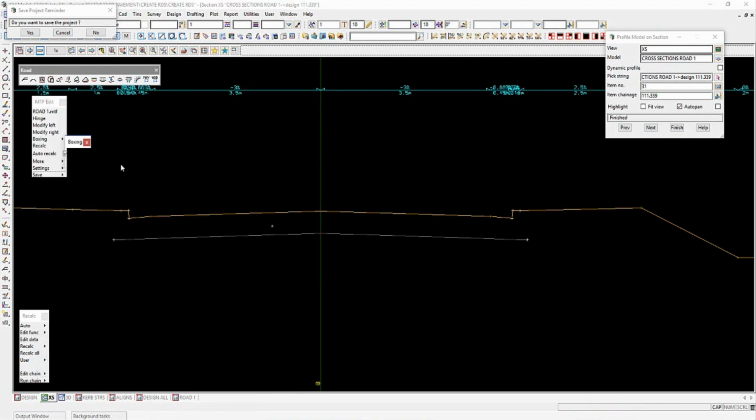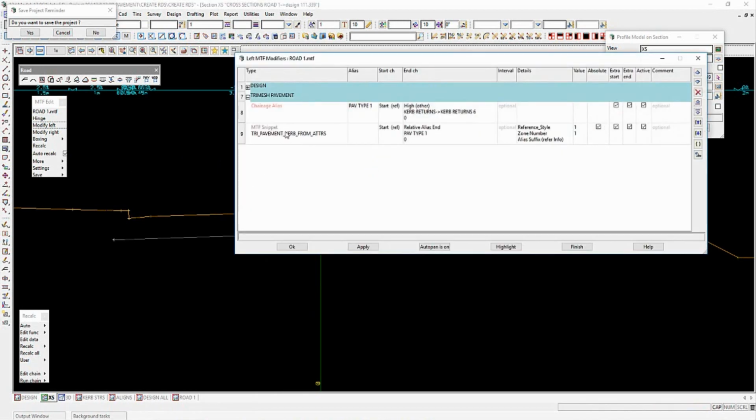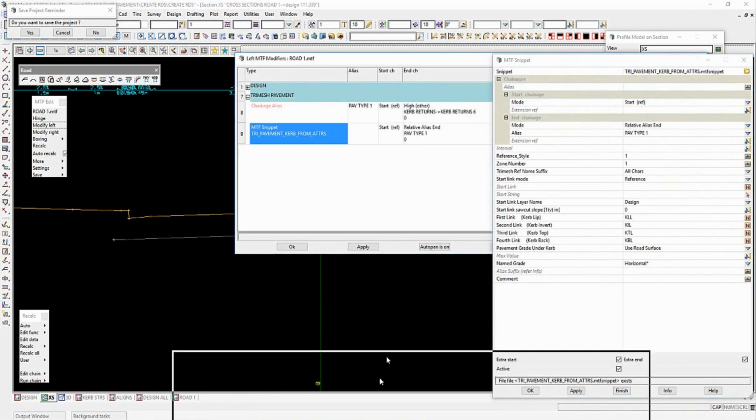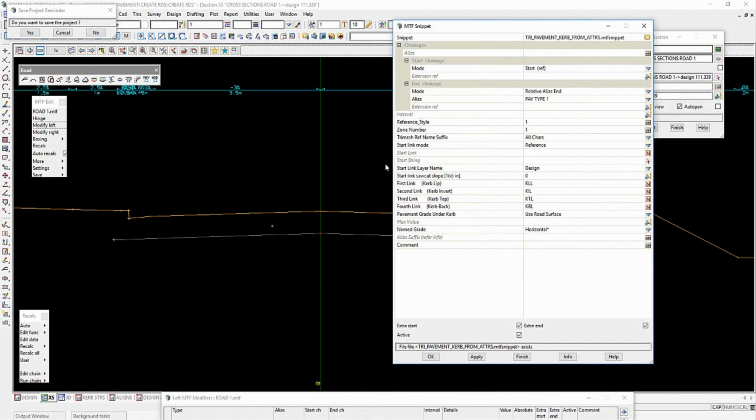So if I look finally at some of the start mode options, it's on the left hand side here. Start mode at the moment is just using our reference line, but we also have the choice to do another cut string. If you have a lane line here, you could use that, but you can also choose a 2D cut string height from design.